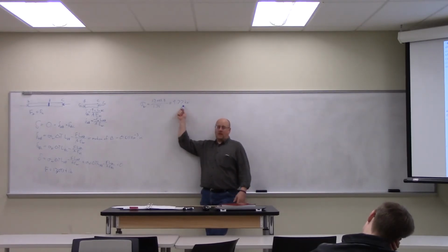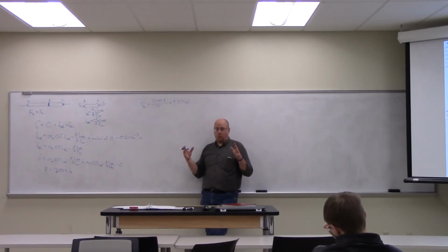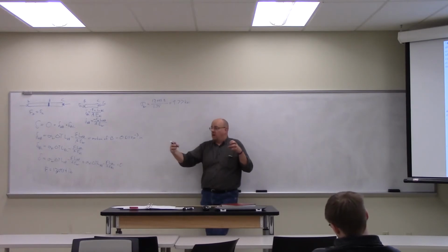So if this was above the yield strength, at 12 KSI, it would have been compacted, and then when I cooled it back down, it would have tried to pull away from the other support, and actually would have been left in what's called a state of residual stress. There would have been a state of residual tension, because if it tries to squeeze back, then superposition would require that we pull it back to the other support.